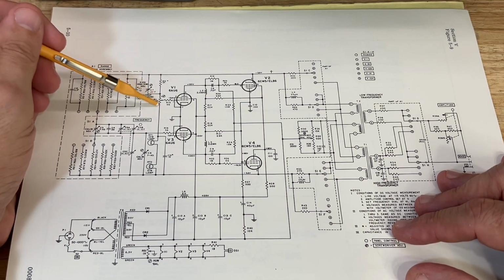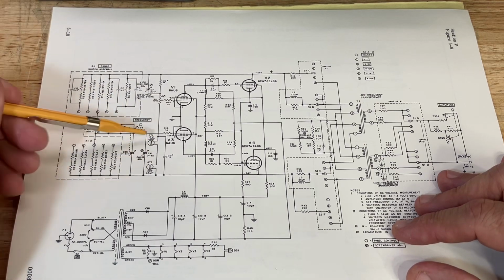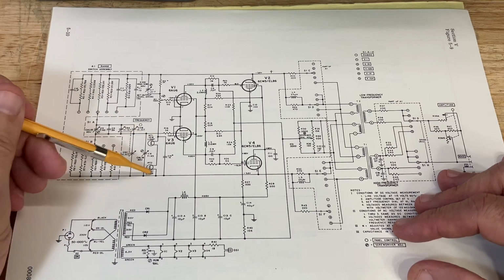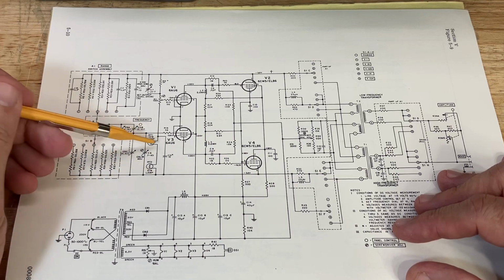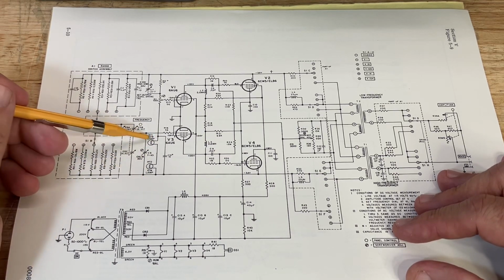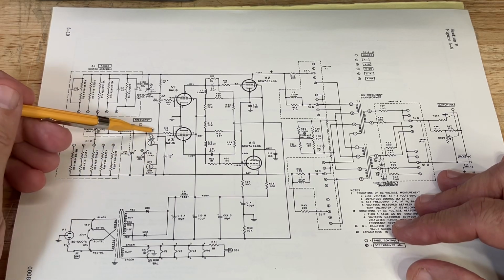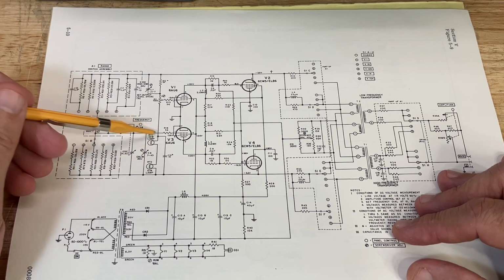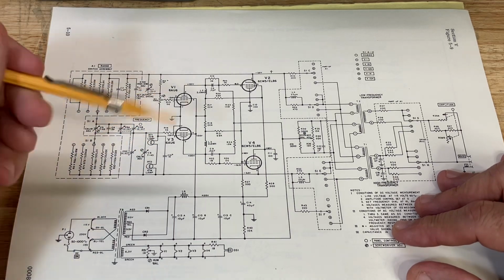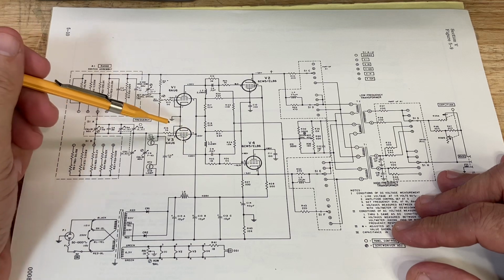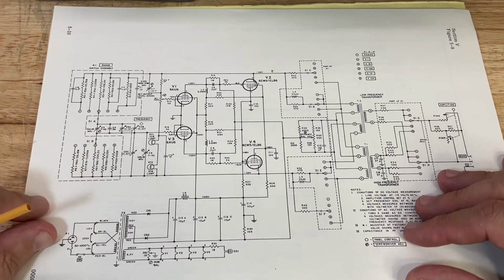and that is adjusted with this variable potentiometer here. And here is the light bulb circuit that we talked about before. A very ingenious way of providing automatic gain control, amplitude control, and minimizing distortion, simply by automatically adjusting the resistance of the light bulb because of the temperature of the light bulb, which is because of the amplitude of the signal applied to it. That automatically adjusts the amount of negative feedback into the amplifier circuit. So that's how the 200CD works.